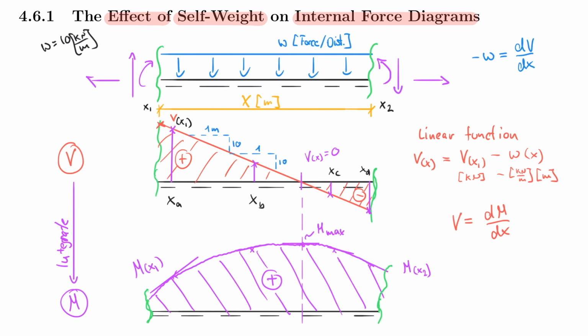So mathematically, students always know this, but really turning this into a shear force to moment relation is sometimes challenging. However, I hope this will help you to clarify this and to understand that this will always work, because we start with a constant function. In fact, let's understand here that this is always a constant. And then, therefore, we end up with first a linear shear function, but then we have a parabolic function for the moment. And that is always true as long as you have a constant or evenly distributed force. So under self-weight, which is really represented by this, under self-weight you will always end up with a linear shear force function and a parabolic moment function.